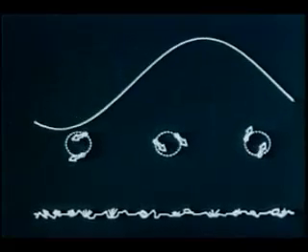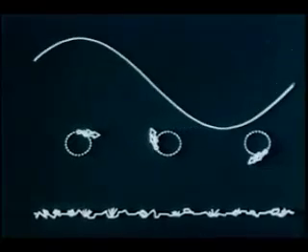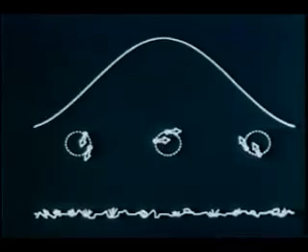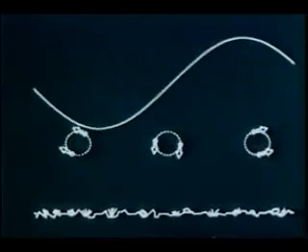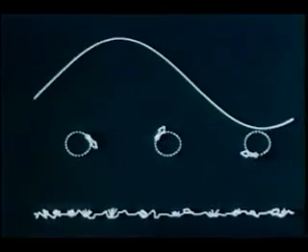In any flow, the Lagrangian field can only be steady if each material point always experiences the same velocity. This degenerate case only happens in a steady parallel flow.